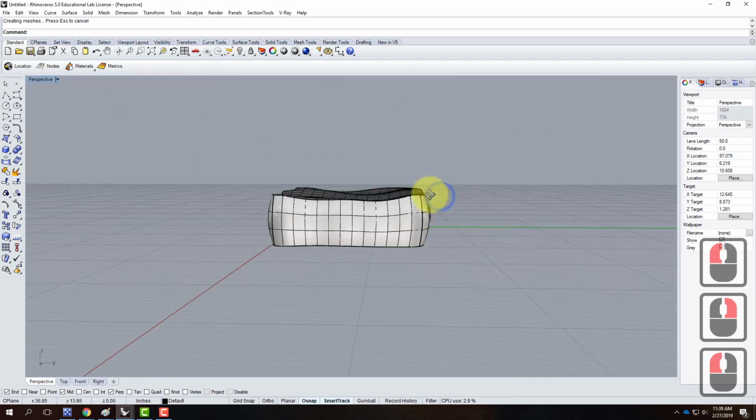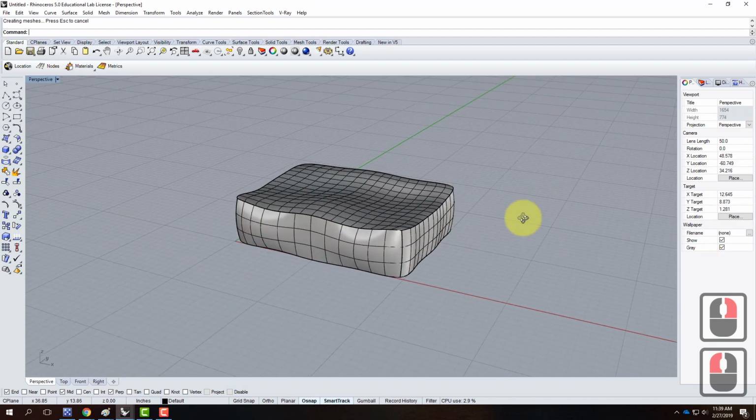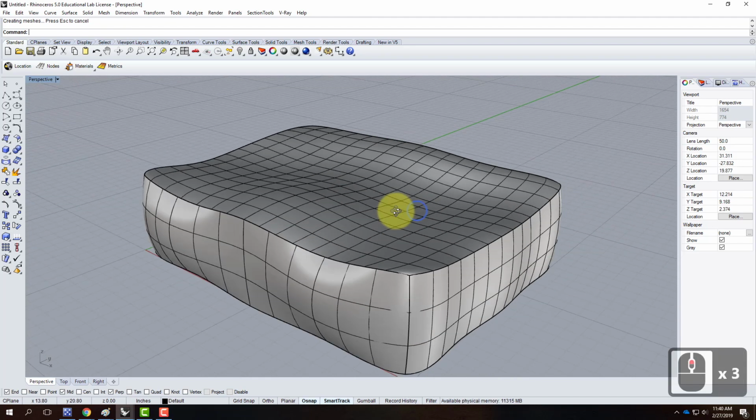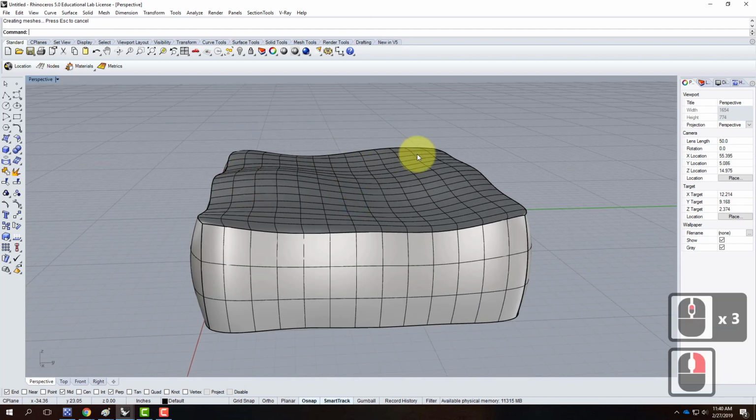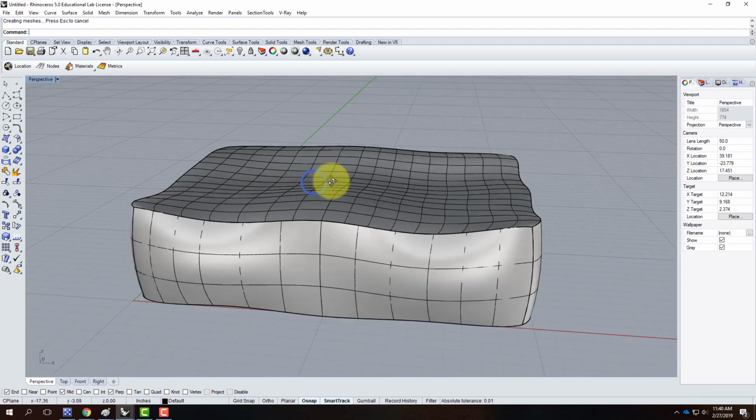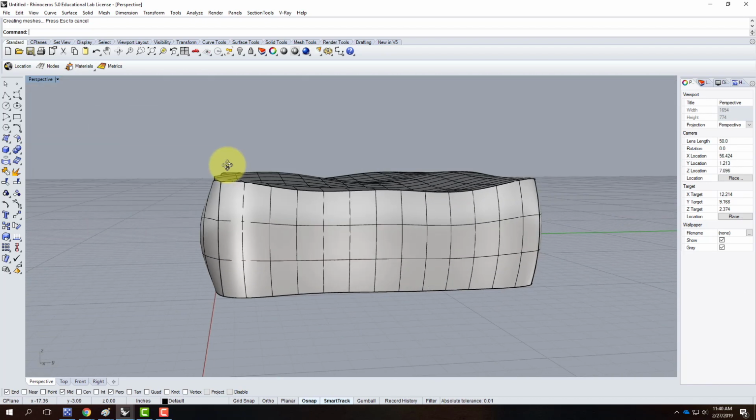So I was able to create a much more organic shape by controlling it with these curves. And that's the important thing to start to understand, is that we're giving ourselves curves that are then controlling the surfaces. And Rhino's doing the work of interpreting the difference between one curve and the other, and how we make a smooth surface between them. So I've created that as the start.